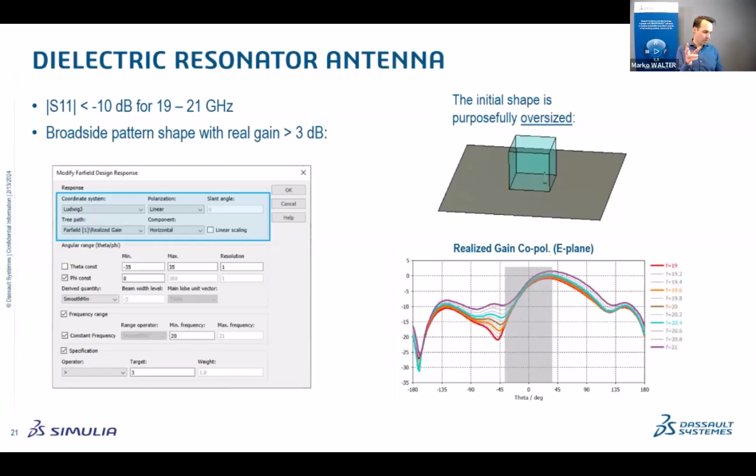So it's a bit different to the conductivity example. This is a loss-free model where we are sweeping from a dielectric constant of 1 to 20. So again, you want to push out those intermediate densities. Then you can also specify the angular range. In this case, I'm taking the phi equal to 0 plane, or the E-plane.